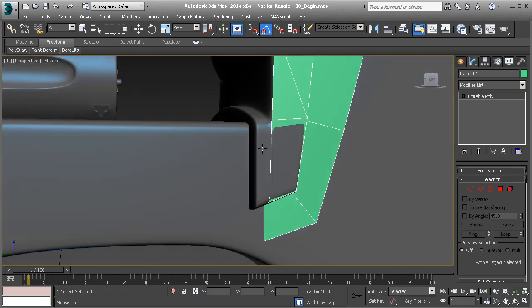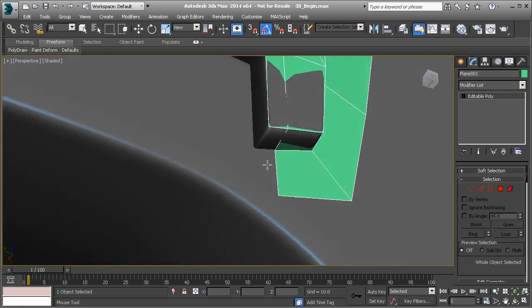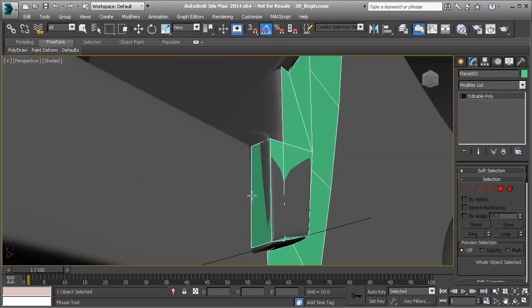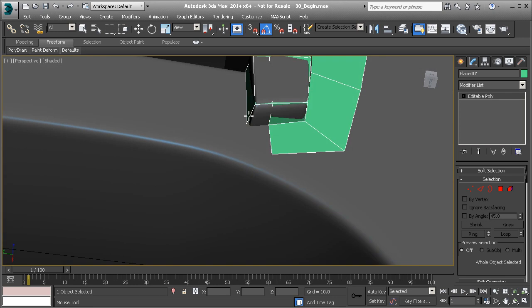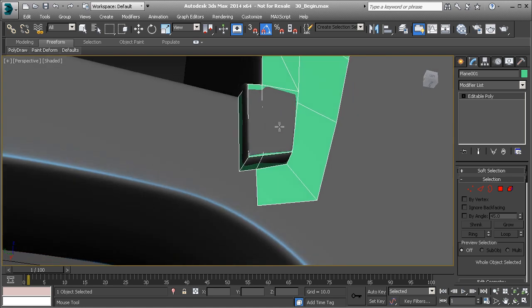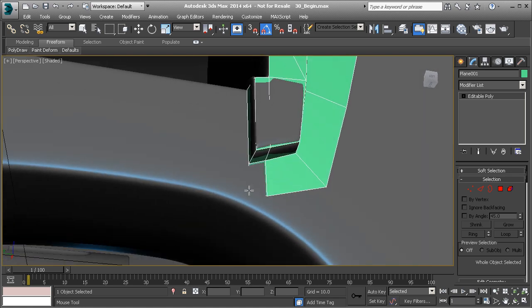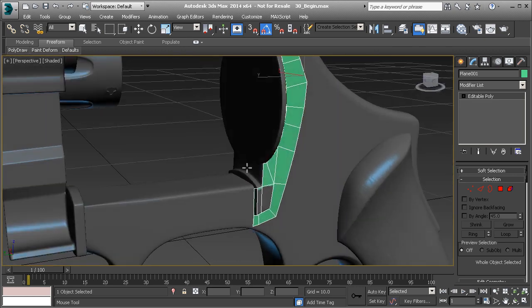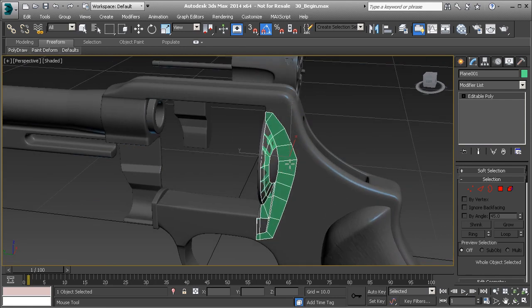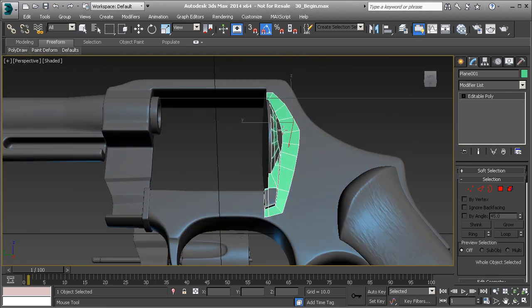And then I'm going to get another surface off of that. So hold down Shift, and then Control Alt Shift to reassociate that. Shift to drag that off of that face there. And there we go. Hold Control Alt, bridge that across there, redistribute those vertices, and then hold Alt, pull that down there. There we go. Okay, so there we've got that side started. So we've got these polygons started here. I'm going to go ahead and stop the video at this point.